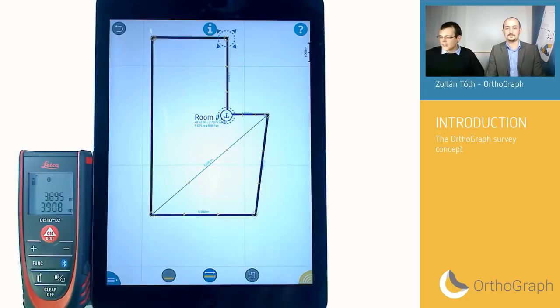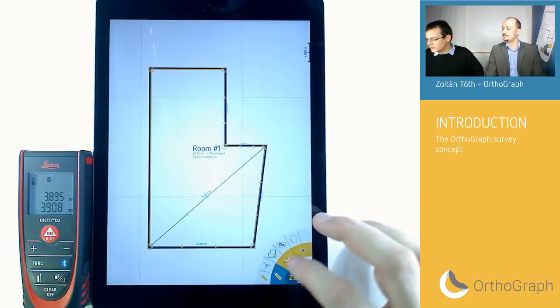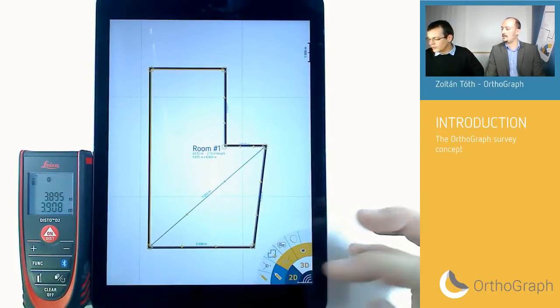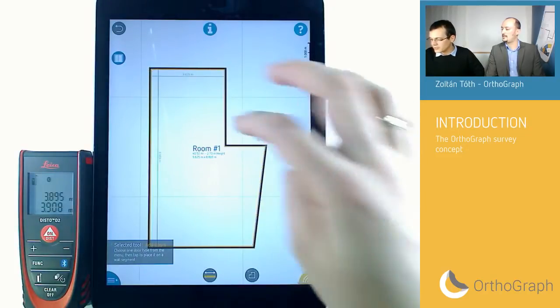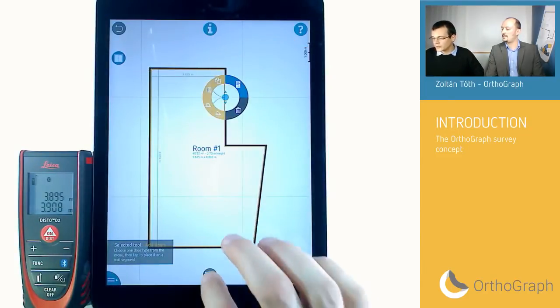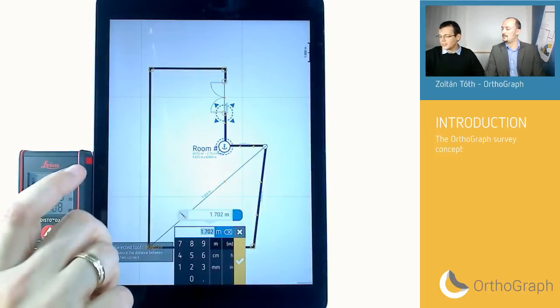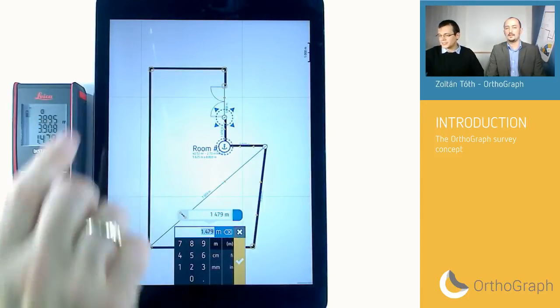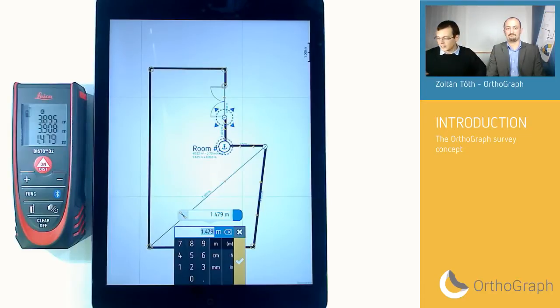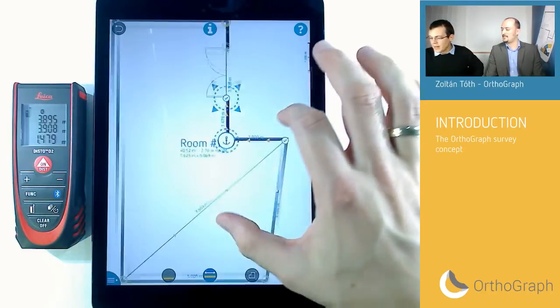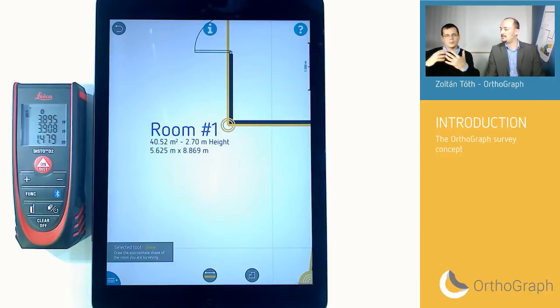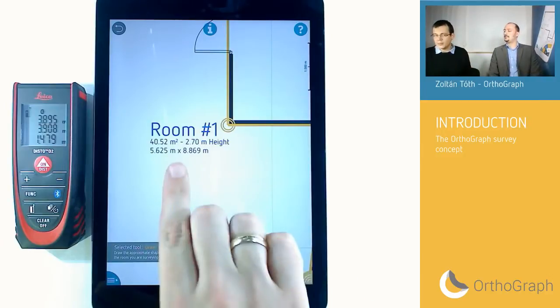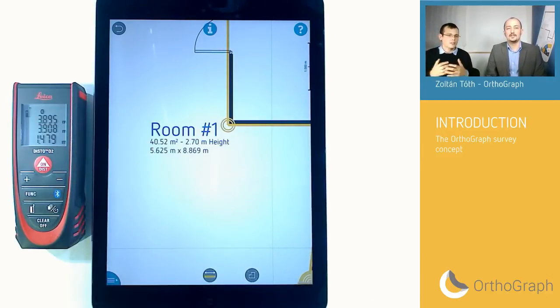Yeah. This cannot only be used for walls, you can also use it for other elements such as doors, windows. If you have a door here, a double wing door for instance, you can just make a measurement, and then if you snap a measurement into the system, you see the same number appearing on the screen. If you modify this drawing in any way, you see that the numbers, which are the locational reports, the estimations, update all the time.